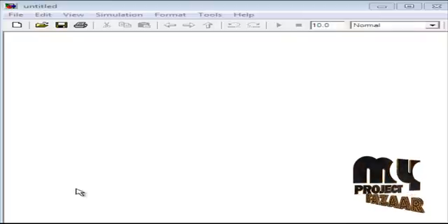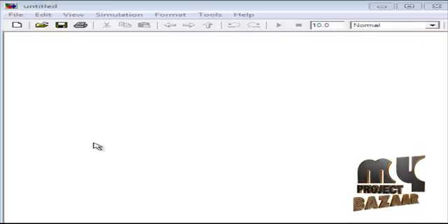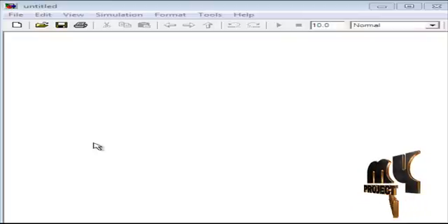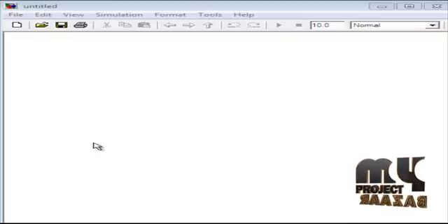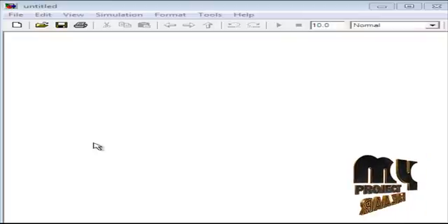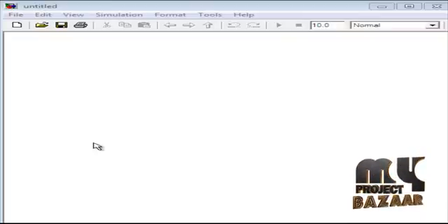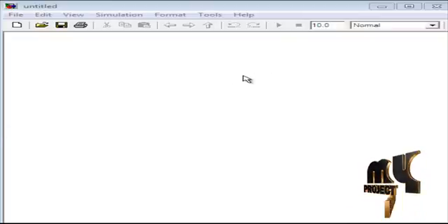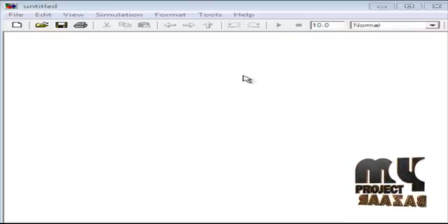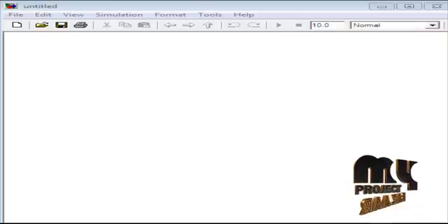The DC to DC converter model takes an input of 68 to 78 volts, and we get an output of 8 to 12 volts, maximum 15 volts. The main part is the buck converter using these blocks, and the main controller is the PWM, pulse width modulation. We are using these controllers, and then the active clamp converters' main steady state analysis.